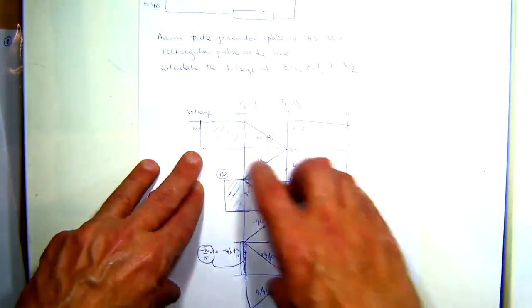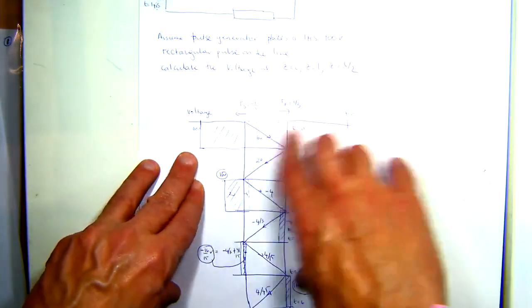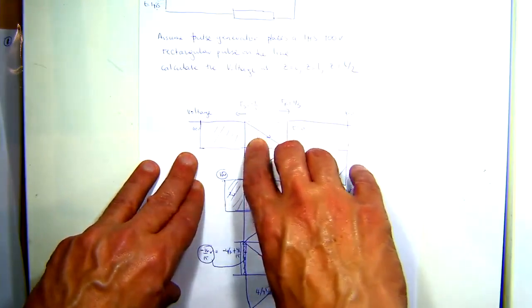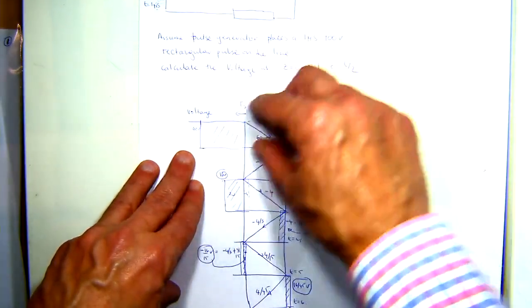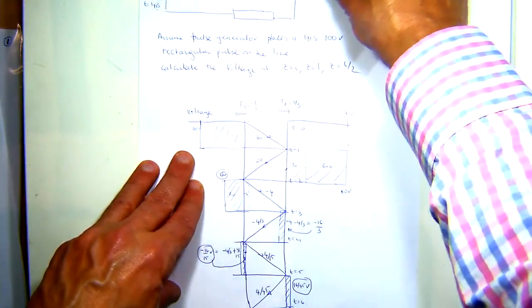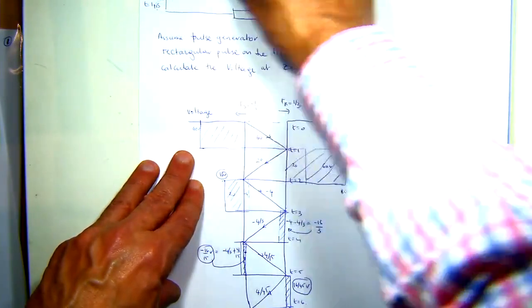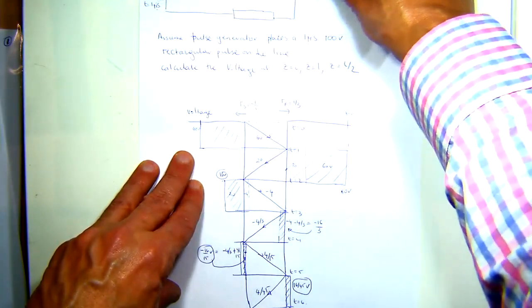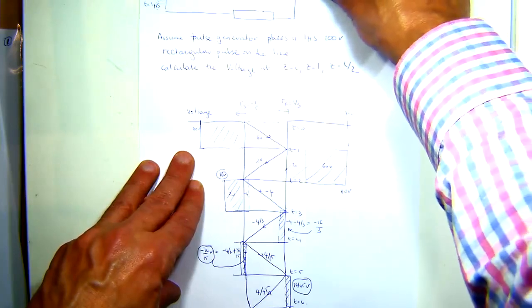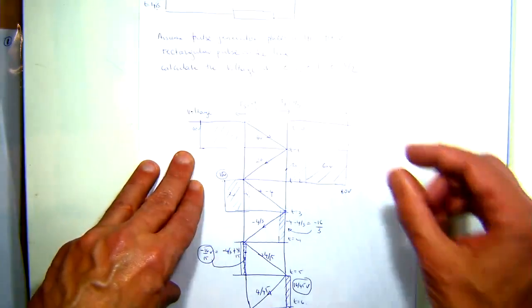Essentially what I did was show we've got the standard bounce diagram, but I also added another dimension here to indicate time. All right, so therefore we've got the 60 volts traveling on the line, and before it finishes there's a signal still on there until it hits completely the other end.